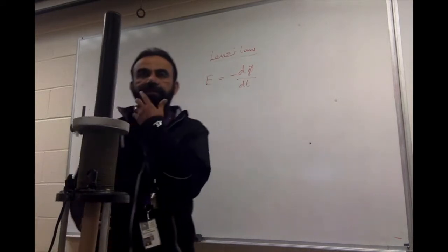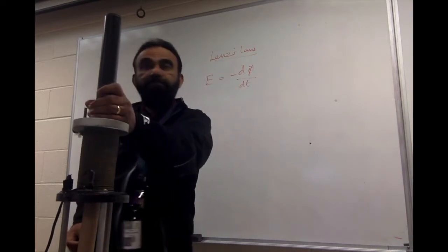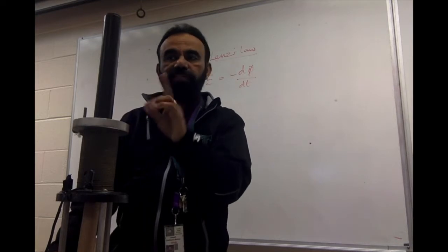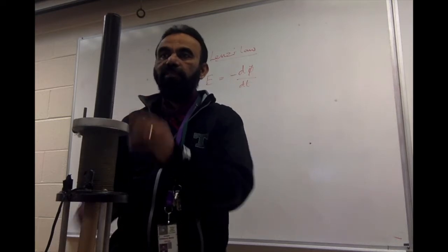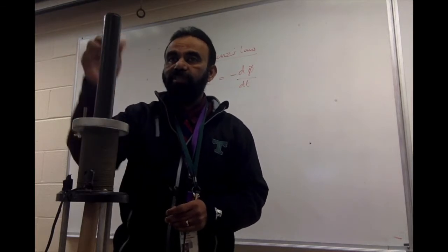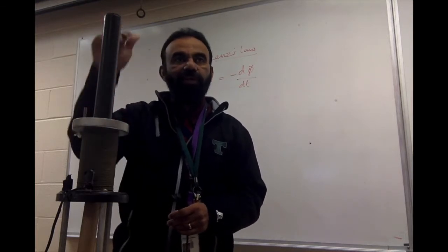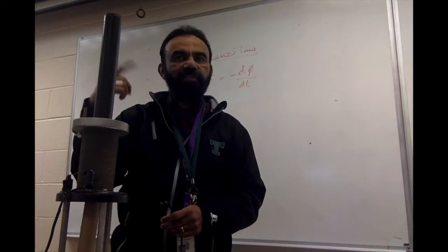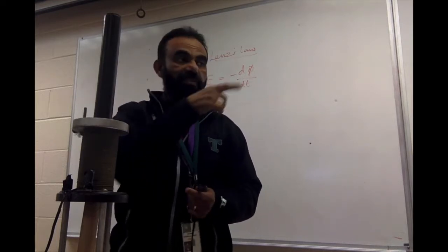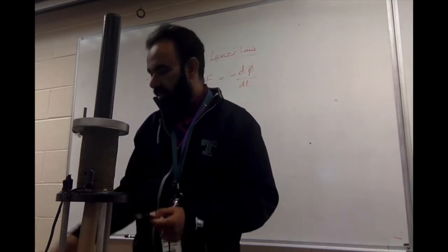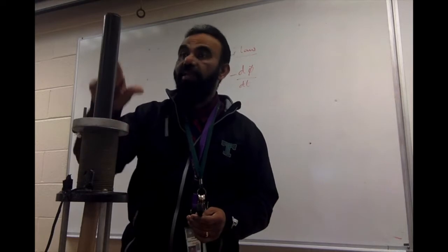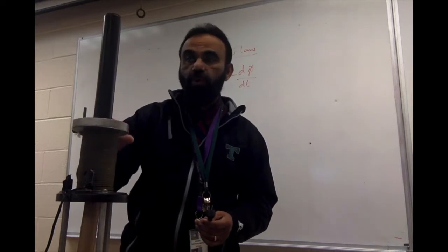it is going to get magnetized, but it is not a magnetism in one direction, it's going to be in both directions because it's alternating. Magnetic flux will flow this way first, and then this way, and then that way, and that way. It cycles how many times per second? 60 times per second. That's a 60 hertz power supply, right? So when you plug it in, the alternating current will produce alternating fluxes in this core.